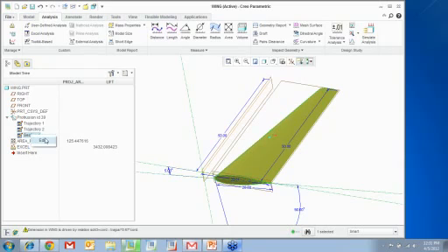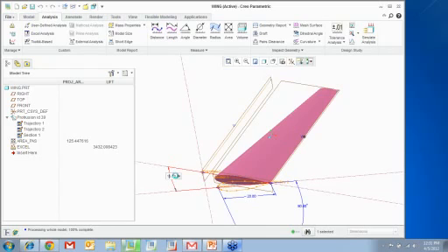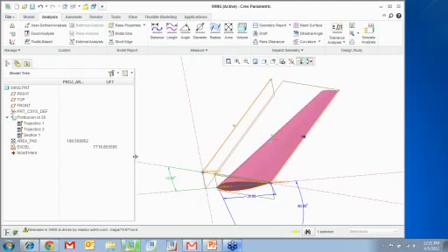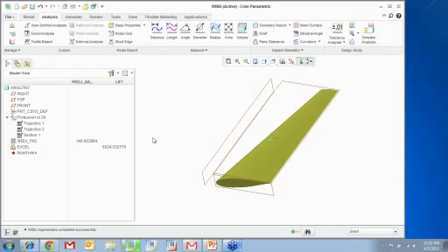So if I go ahead and edit this value to say I want to go 15 degrees, like that, you can see how your lift and your projected area change. You can go ahead and make it 10 degrees, and you can see how your area and your lift force change. Right? So we can use an Excel file to determine a lot of things within our design. Okay? So that was Creo Simulate and Creo Excel analysis.